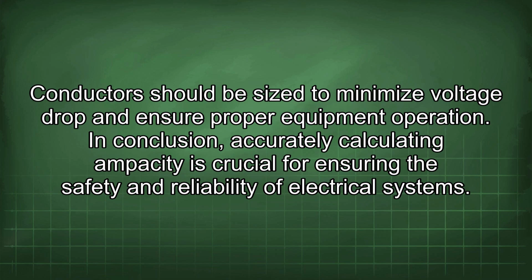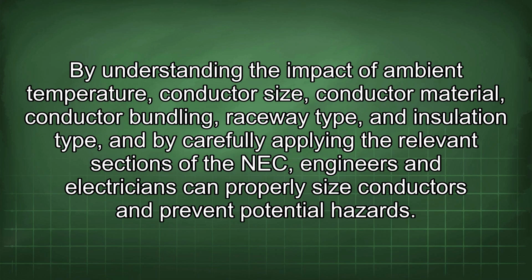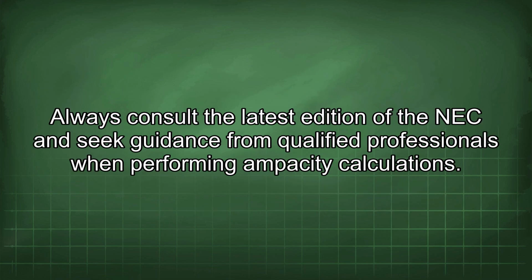In conclusion, accurately calculating ampacity is crucial for ensuring the safety and reliability of electrical systems. By understanding the impact of ambient temperature, conductor size, conductor material, conductor bundling, raceway type, and insulation type, and by carefully applying the relevant sections of the NEC, engineers and electricians can properly size conductors and prevent potential hazards. Always consult the latest edition of the NEC and seek guidance from qualified professionals when performing ampacity calculations.